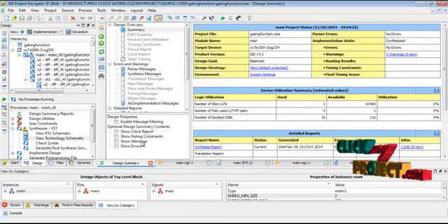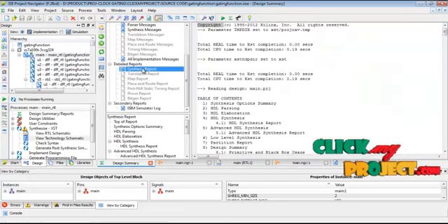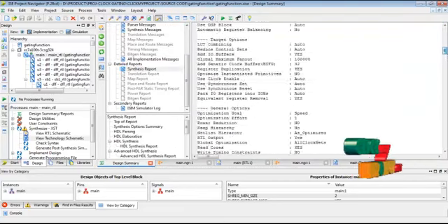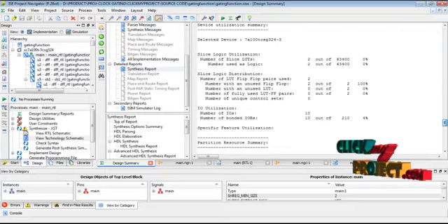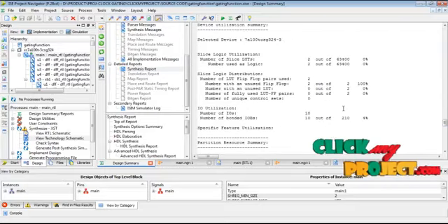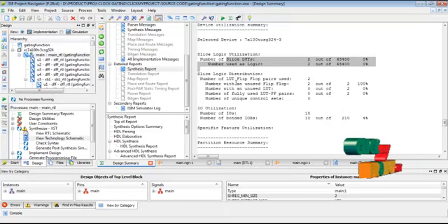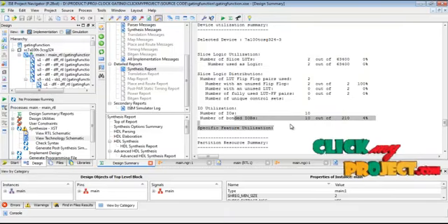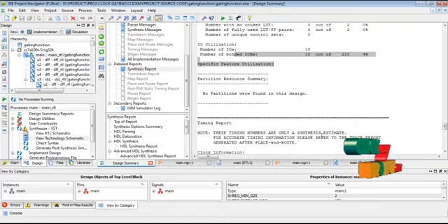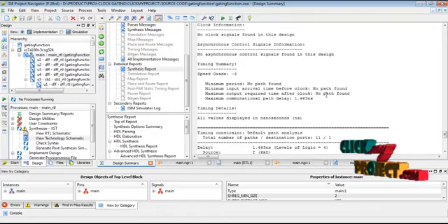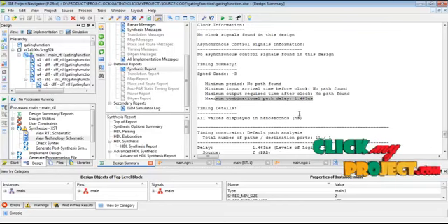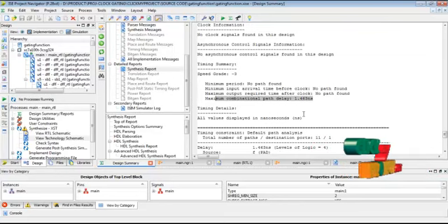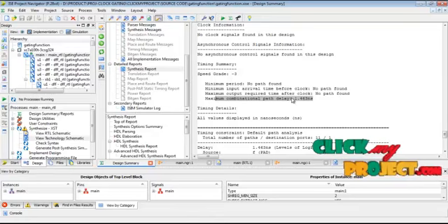Then calculate the design summary. The design summary synthesis report generates the processing area for device utilization. This is the lookup table and flip-flop pair. Then the bonded input/outputs are mainly based upon the area of the clock gating architecture. Then the timing summary: the delay time of 1.463 nanoseconds is the overall running time of the clock gating architecture process.